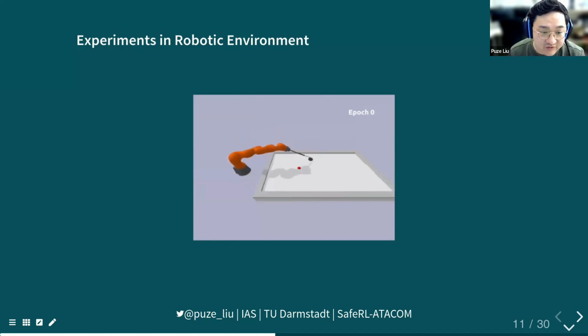We also add some other constraints in the joint space, for example, ensuring the joints stay within their limits and the velocity stays within the velocity limits. Another constraint tries to ensure the elbow of the robot doesn't collide with the table. So in total, there are 20 constraints in effect in this task.